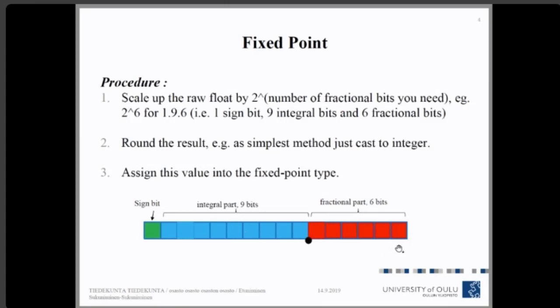An extreme example would be that we stretch the fractional part up to the 14th bit, starting from bit 0, and then we just dedicate 1 bit to the integral part.